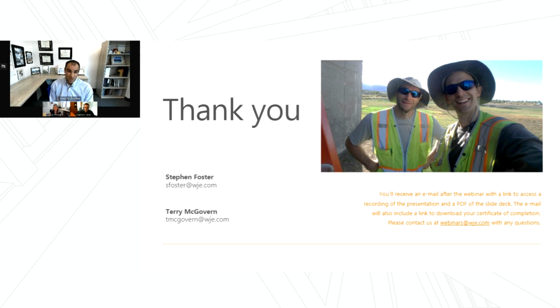And I think that's the key, right? It's about getting things done properly, mix design through placement and curing and everything like that. Certainly challenges with lower heats of hydration can cause issues in colder climates at times, right? When people aren't expecting to need to provide as much heat. So where those go for durability long term, I think in the field we'll wait to see.